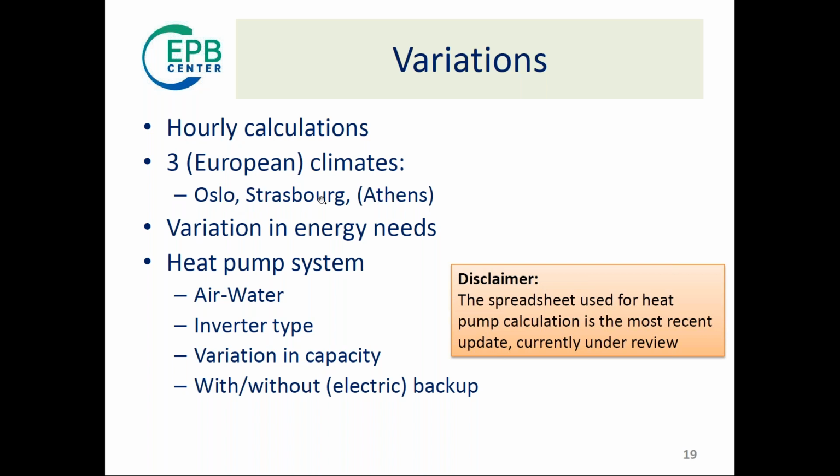For the heat pump, heating in Athens is less interesting. Variation in energy needs, and for the heat pump system, we selected an air-water heat pump system, so using external air. Inverter type, we have in mind to apply a variation in capacity and with or without an electric backup.